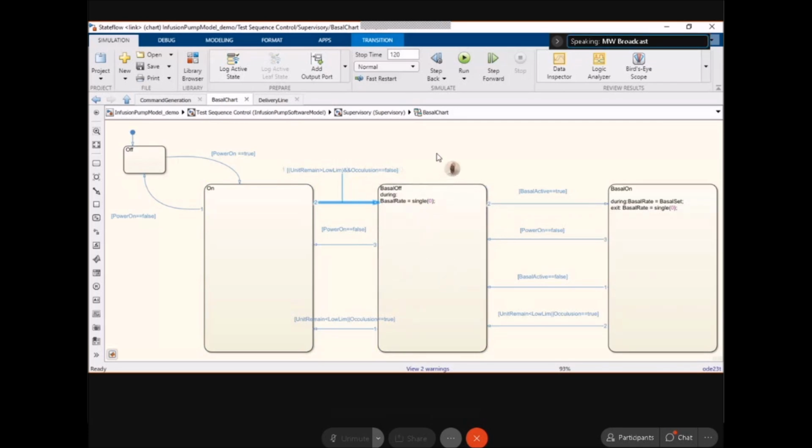Right. So Stateflow really is an add-on for building those state machines, and those state machines are great for applications like this one where I might need supervisory logic. And as you mentioned, Karan, we have 4 states, but we're changing states with these transitions that are evaluating inputs or certain constants, and depending on what state I'm in, then the system will behave in a certain way.